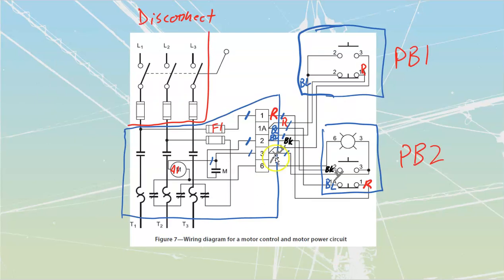We're then going to go back into this one over here. Once again, we are going to go and look for what wires we have not identified. Do we have anything connected to number 6 yet? Not yet. We haven't gotten that far. Do we want to start working from number 6? Maybe. It might make sense to start working from number 6. We can at least trace it out, but the problem is we don't know where either end of number 6 goes. So at this point, what we have done is we have identified all these devices up to a point, but we haven't identified opposite sides yet of these devices.